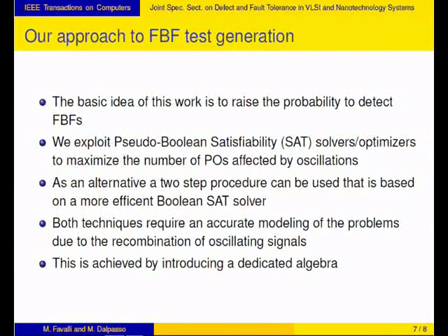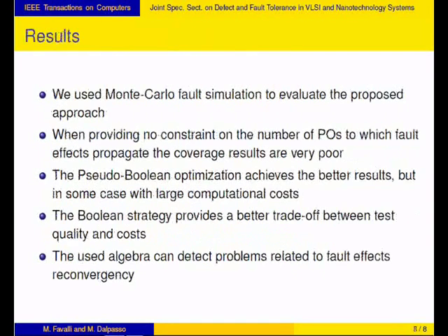Both such techniques require an accurate modeling of the combination of oscillating signals that is achieved by introducing a dedicated algebra. The proposed approach has been validated by using Monte Carlo electrical and logic level fault simulation to account for delay variations in small and large benchmarks, respectively. We first observed that test generation with no constraint on the number of primary outputs to which fault effects propagate provides a very low detection probability.